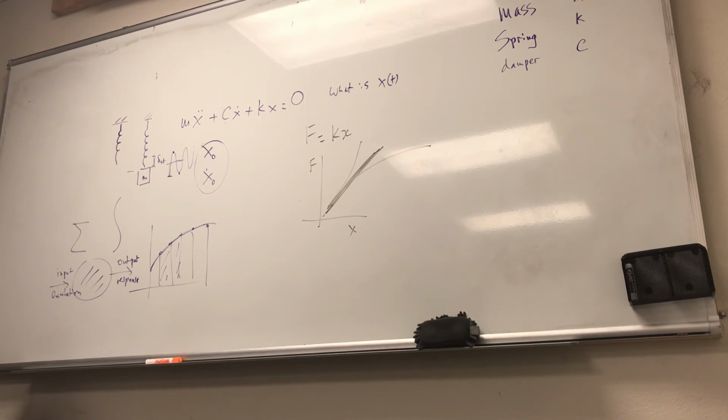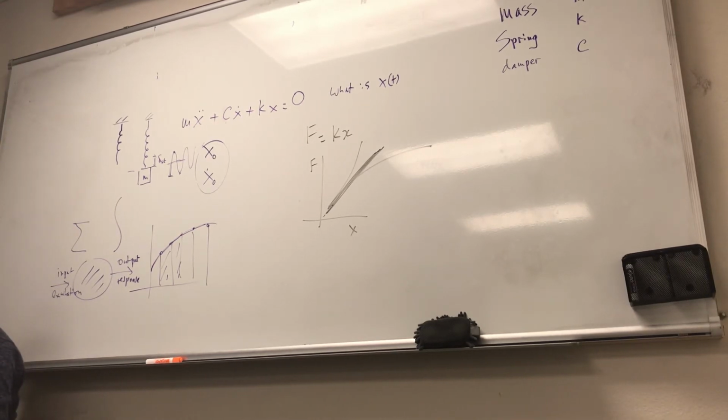Okay, now that we have the mathematical model done, what's the next step? Next step is to derive the equations, the derivation of the governing equations. What do we do with that? Well, we use the principle of dynamics, which is nothing more than sum of forces equal ma, to derive the equations. Or sometimes we can use energy methods too. If there is no damping, we say the total energy is constant, and take derivatives. I'll show you how to do all that later, and then come out with the equation.